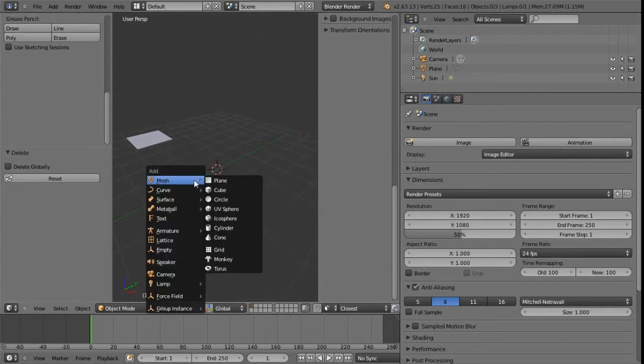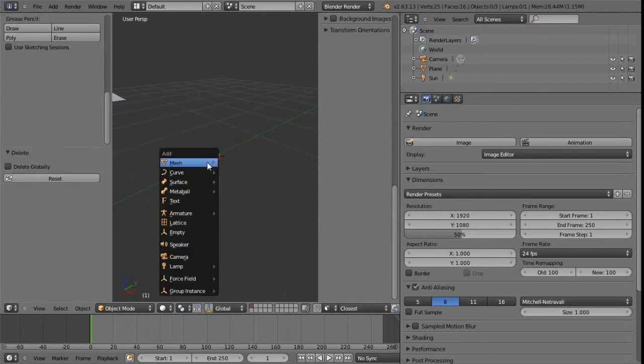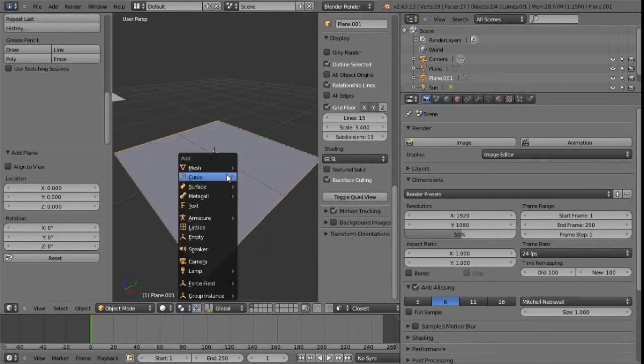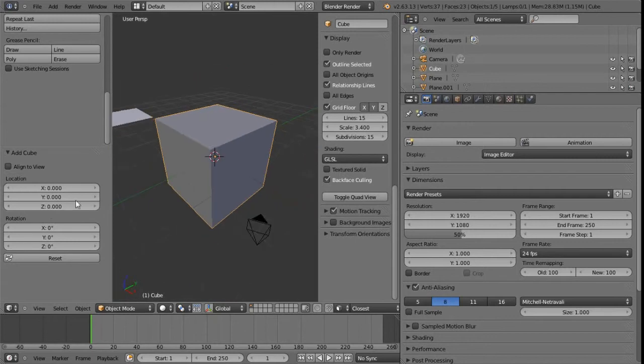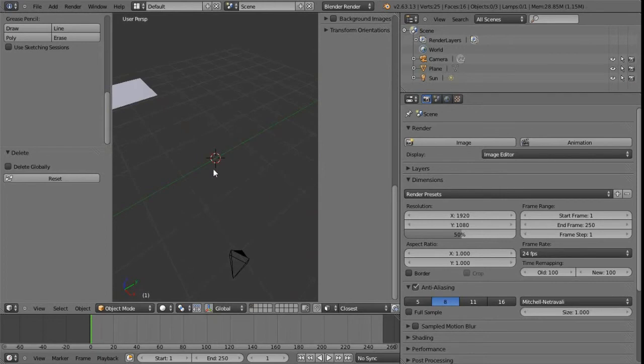Also, it's most commonly used for the smooth surfaced objects like the sphere or a circle, when we get to choose exactly how dense we want that to be, the kind of resolution, in a sense, of this spherical object. So that's just worth noting. The more angular meshes, for example like the plane and the cube, don't by default come with things that we can then alter the subdivisions of in that single operation. So just bear that in mind.